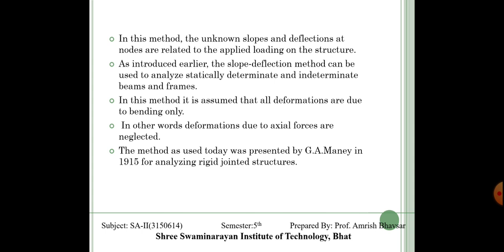In this method, it is assumed that all the deformations are due to bending only. In other words, deformation due to axial forces is neglected. The method as used today was presented by G.A. Maney in 1915 for analyzing rigid joint structures. Here we are considering that all the joints of the frame are rigid.